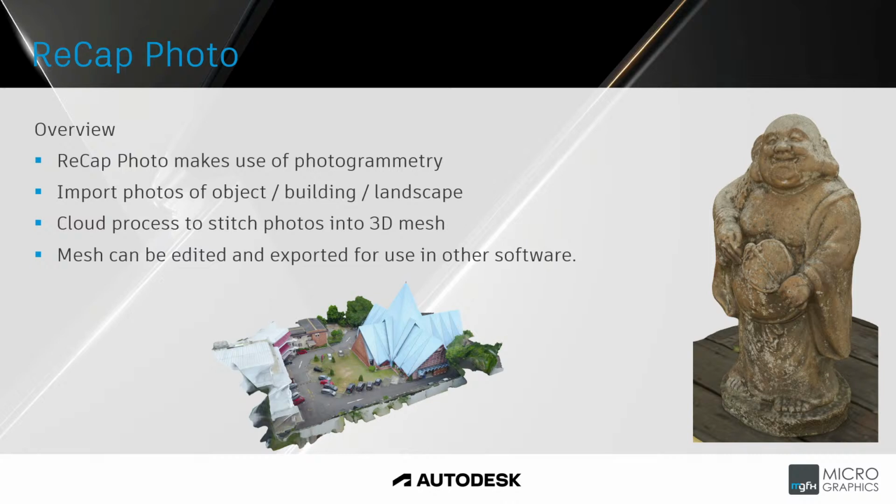Now, the photogrammetry portion, or that process of photogrammetry, can be used to create a 3D mesh file, typically an STL file, of objects. They could be small objects, sort of the size of a cell phone, potentially even smaller, all the way up to large scale buildings, construction sites. And the size of the object is going to determine how you should take the photos. So if you're doing small objects, you can use any sort of handheld camera just without autofocus. You want to have a fixed focus point essentially to have better results, and you would take the photos.